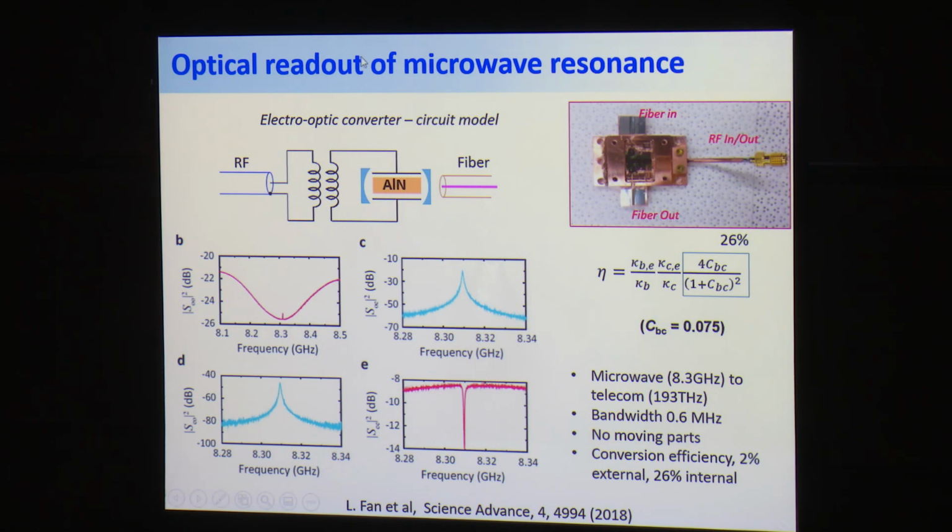So now you have this converter device with two ports. One is an RF port, the other is an optical port. You send your carrier in over here and look at the sideband of your carrier. So you can send an RF signal in, okay. You demodulate the optical carrier. You see this conversion from microwave to optics here. Or you can do the backward, send the optical sideband in and measure RF power.